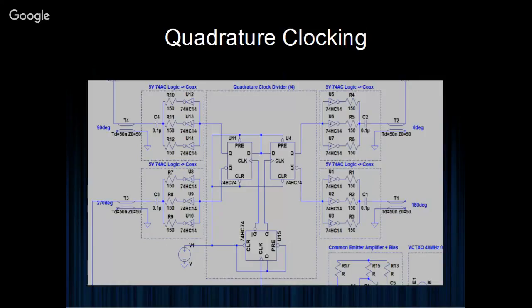So you need to look at the maximum deliverable current per gate, and in this particular package, the 74AC14, the maximum deliverable current source or sink is 50 milliamps. So you obviously don't want to meet or exceed that.